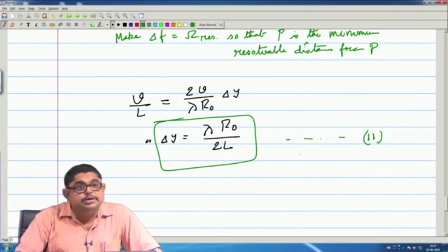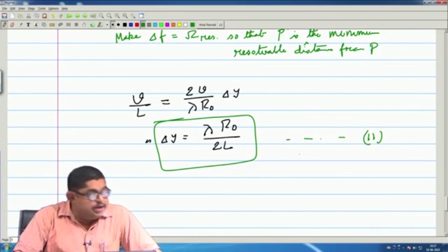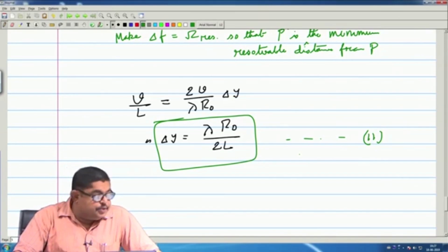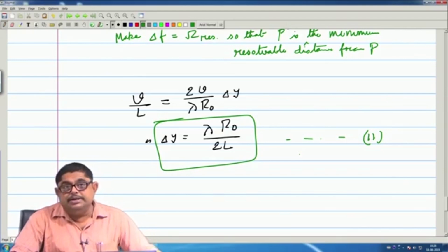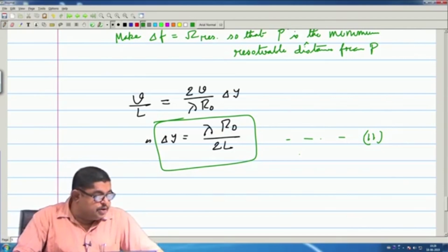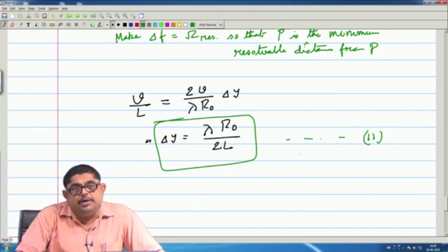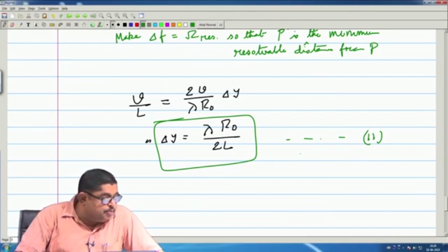So, the radar echo signal is not a constant frequency signal. The Doppler filter in the receiver will have to differentiate these two linearly varying frequencies close together, but with present days electronics that is not a tough problem with digital filters.